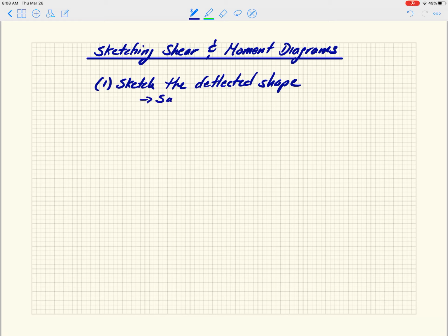And there's a couple rules here, right? Rule 1 is that you must satisfy boundary conditions and continuity conditions, right? So if two members come together and there's a hinge, well, they have to have the same displacement at that hinge. It doesn't have to be zero, but they can have different rotations, right? So there can sort of be a kink in the deformed shape.